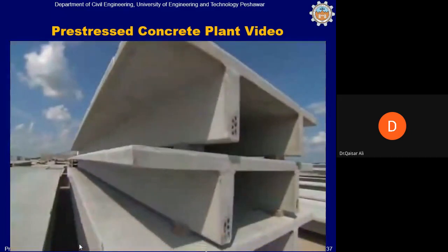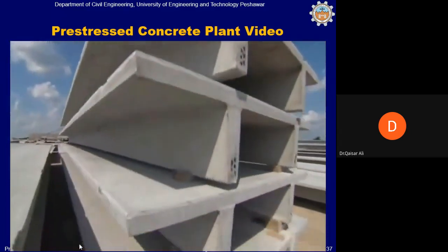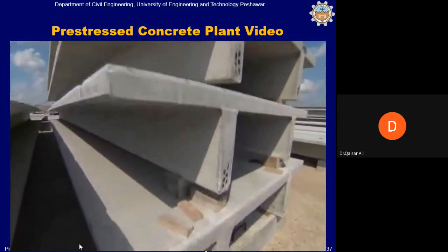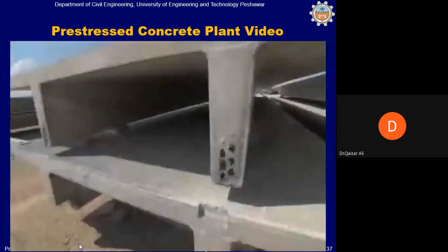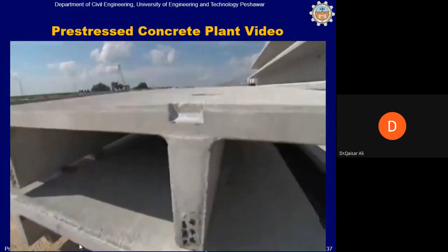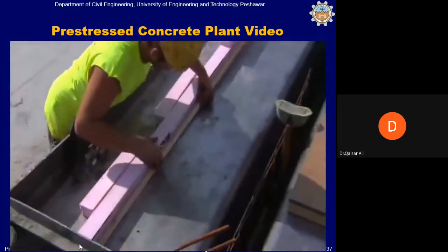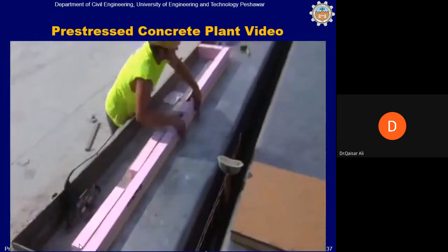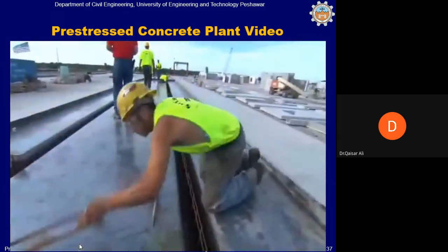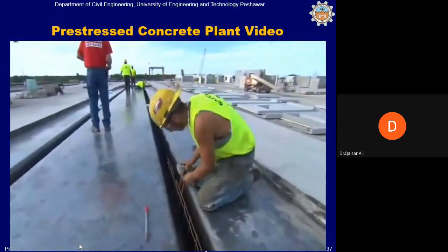Double Ts for parking garages really need to be held to a high standard. When they're assembled in a garage, they make the finished surface. There are tolerances for putting these pieces together, offsets in the surfaces. All of the connections are very sensitive as well to be executed properly. The embedments in the double T have to be placed properly. So there, again, are a lot of critical issues that you have to be concerned with to get proper performance out of that simple double T.